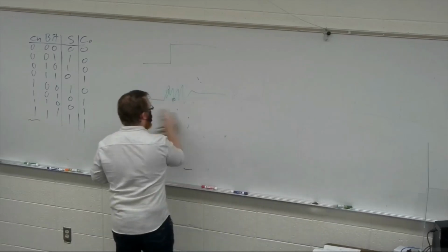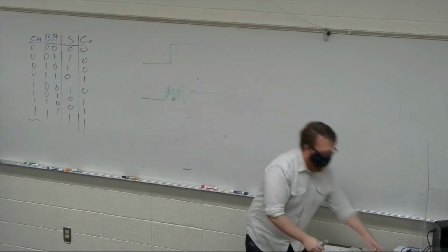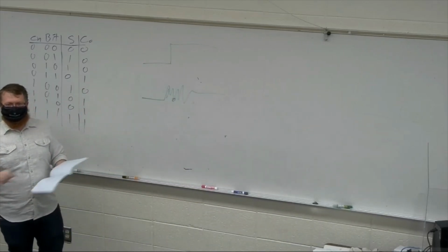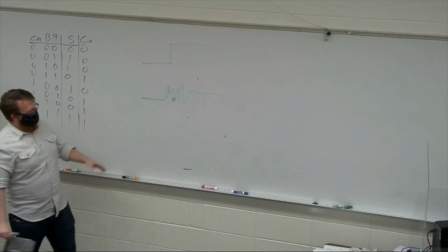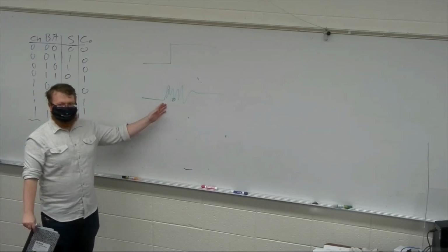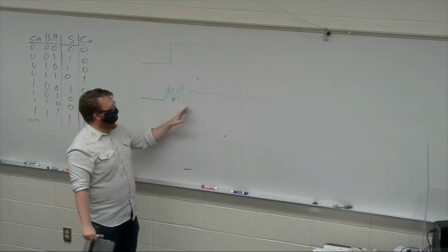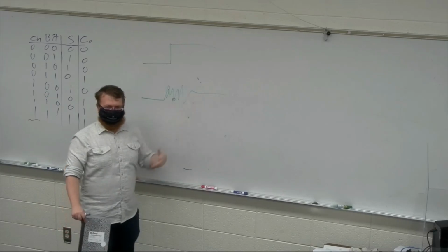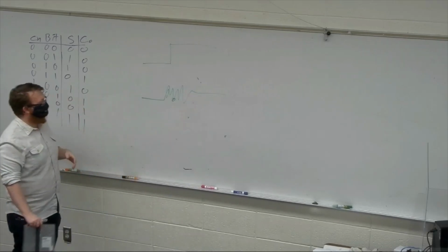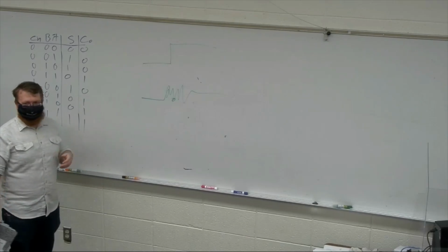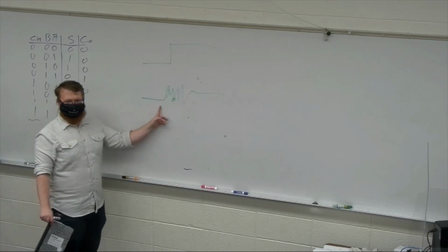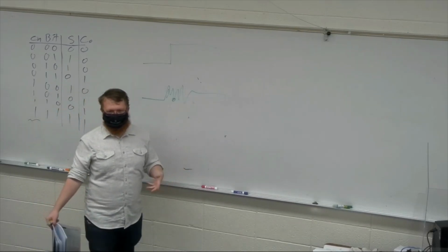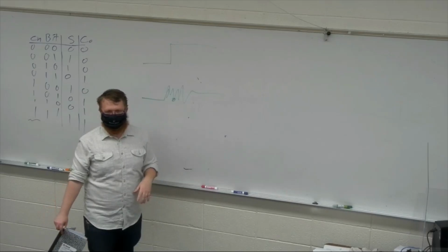is, well, there's two of them really. One of them, the method that we might use because we love state machines, is to design a state machine. It detects a rising edge, waits for a little while, and then samples, right? The other one is to do that exact same thing. I just always call it the click count sample method. So you click your switch, you count for a little while, and then you sample. It's very similar to the state machine method, it just uses a counter instead of a state machine tool.